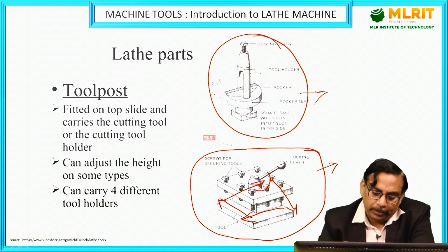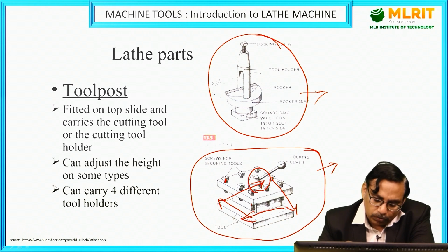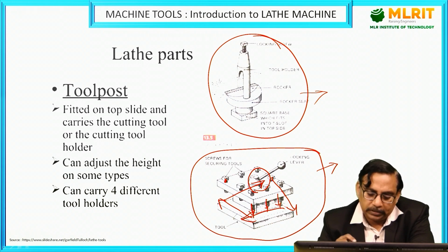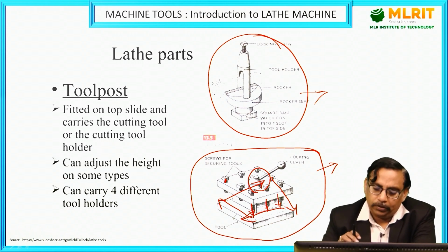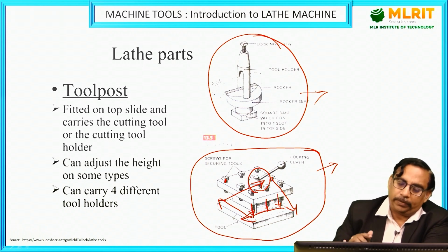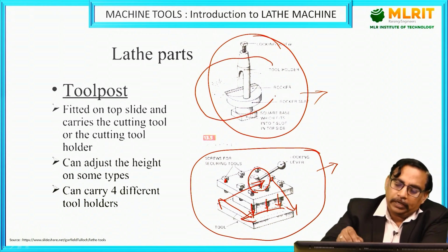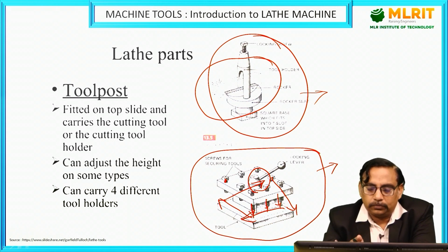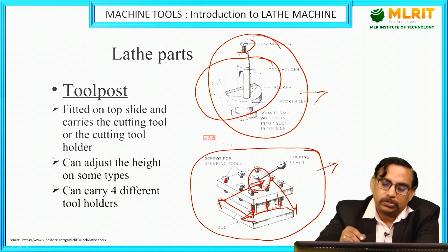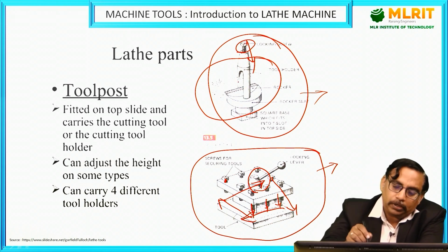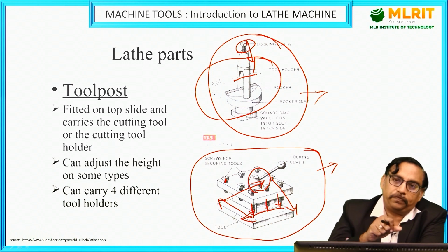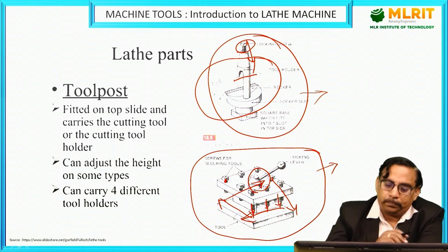So it will be having a locking lever such that it cannot rotate at all, and these small screws are utilized such that they will be rotated downwards onto the shank of the tool, such that it will be fitted perfectly and won't move while machining operations are done. Even the cutting tool holding part will also have a locking screw, which can be rotated downwards such that it touches the shank, and when we fit it, there won't be any movement of the tool.